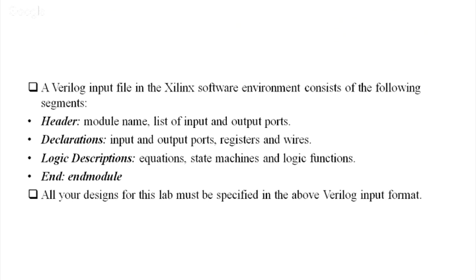Now, what are the steps when we are writing a Verilog program on Xilinx? The Xilinx environment consists of the following segments. First of all is the header. Header means we give any name to your project. It is called the module name, with the list of inputs and outputs which we use in your project.